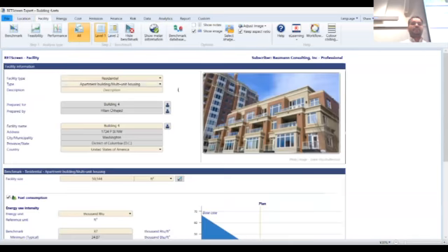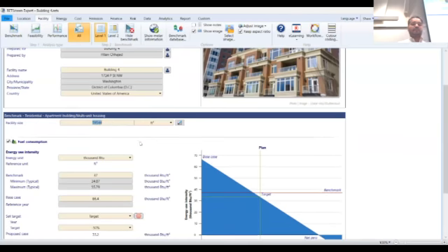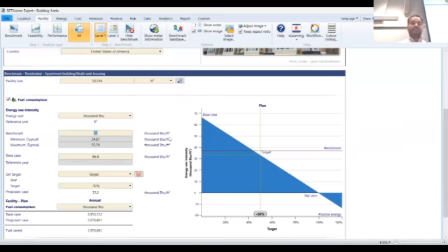Next step is for us to define what type of facility it is, right? For us, it is a residential property, a multifamily building. For the location of the property, we specify the square footage, and we know the current baseline case. This baseline case is something that we are getting from Energy Star Portfolio Manager: what is the building currently consuming in terms of energy usage? So accordingly, we understand how the building is performing. Benchmarking is what the BEPS requires in order to comply. So we are setting a target a little bit above the compliance requirement so that it is meeting the BEPS.